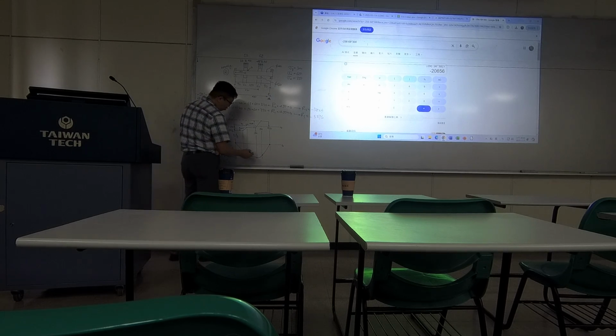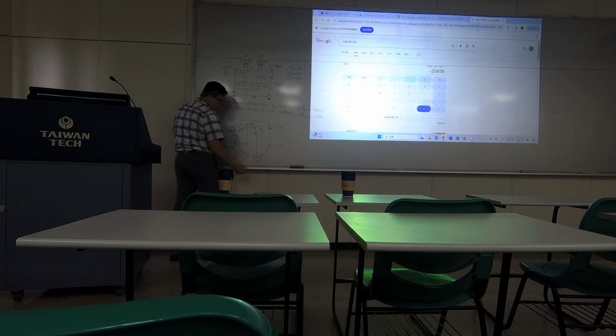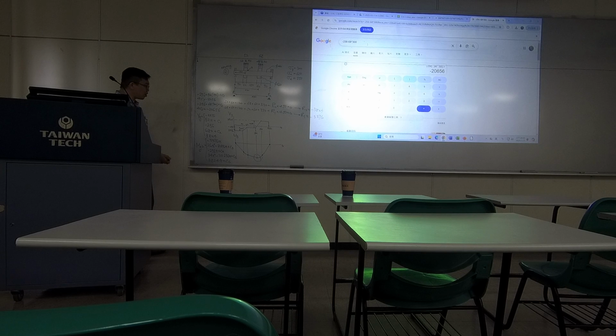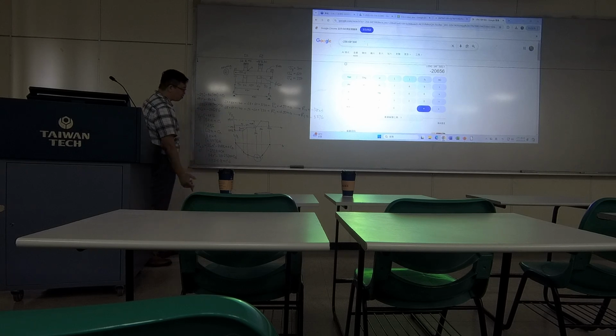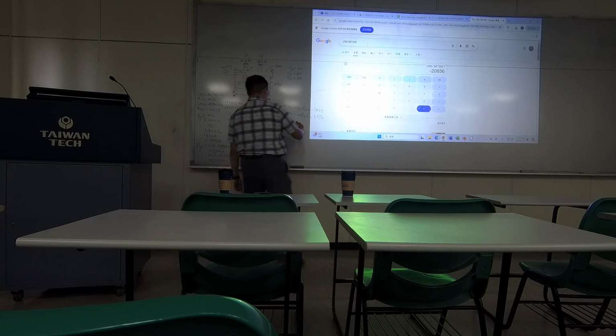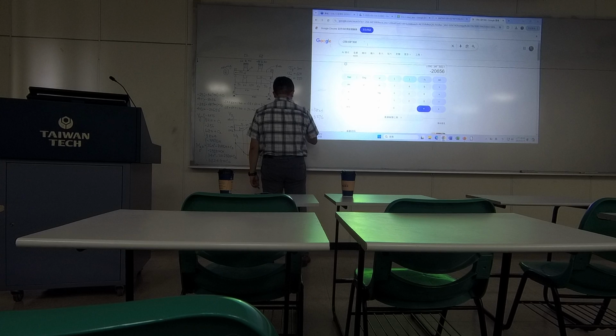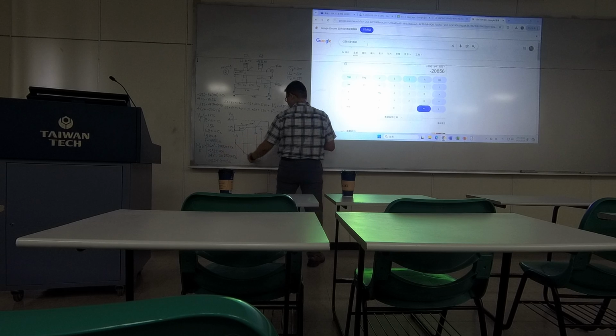So the worst bending condition will be somewhere close to here. It's either at the intersection between part 3 and part 4, or somewhere at the bottom of part 4. So we can try to solve for the minimum value of part 4. If you take the derivative of part 4, then you can get the slope.